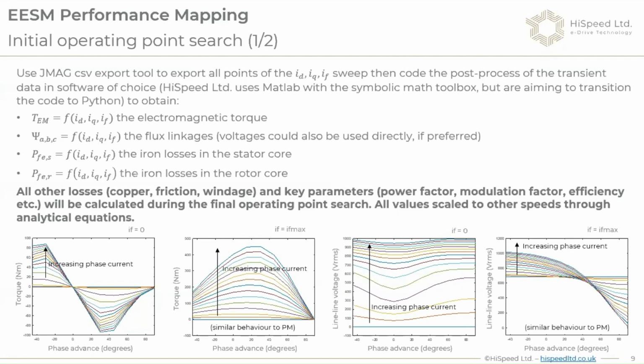And we've had a lot of difficulties at the beginning with the optimizer finding the right point. So we always had efficiency maps pop up with a couple of points where data didn't make sense. So we ended up really scripting our own optimization routine rather than using something that was predefined in MATLAB, for example, the function fmin_con. So I think that's a very important point of processing the data with the WSM: try and find an algorithm that is suited to the WSM, which is kind of a mix between synchronous reluctance and permanent magnet type behavior, whether we're going from low field current to high field current.